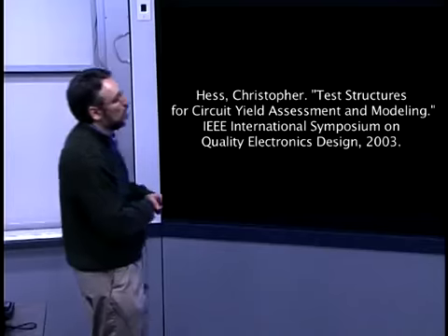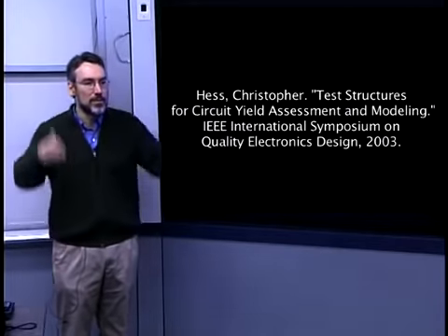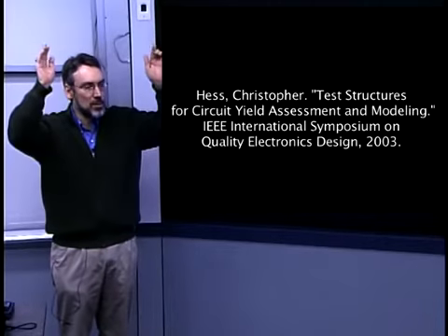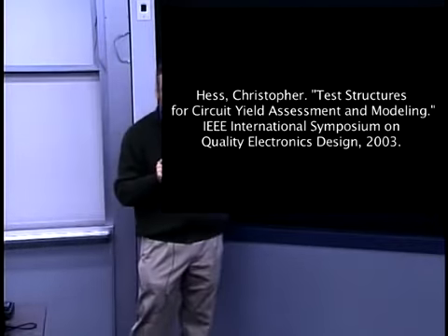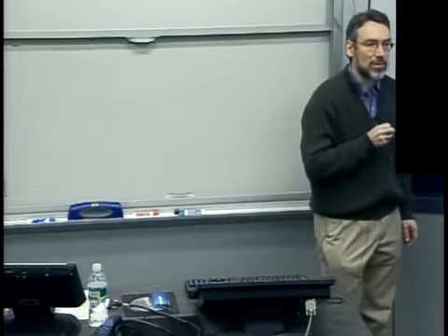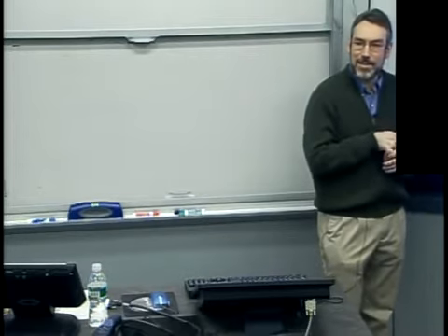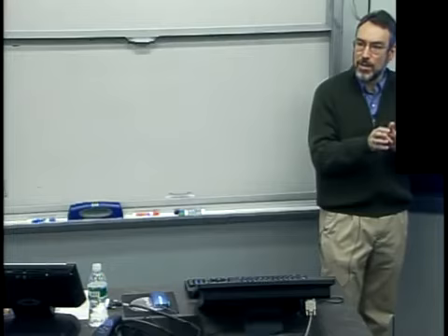And that's why if you go into an IC fab, it's a clean room, everybody's wearing clean room garments, there's incredible amounts of airflow to filter out and remove all kinds of dust particles or other extraneous matter down to very, very tiny dimensions. That's really the measures that have been taken in order to get the cleanliness you need in order to not eliminate, but get those particles down to a particle density and down to a size that are small enough not to have too big of a yield impact.